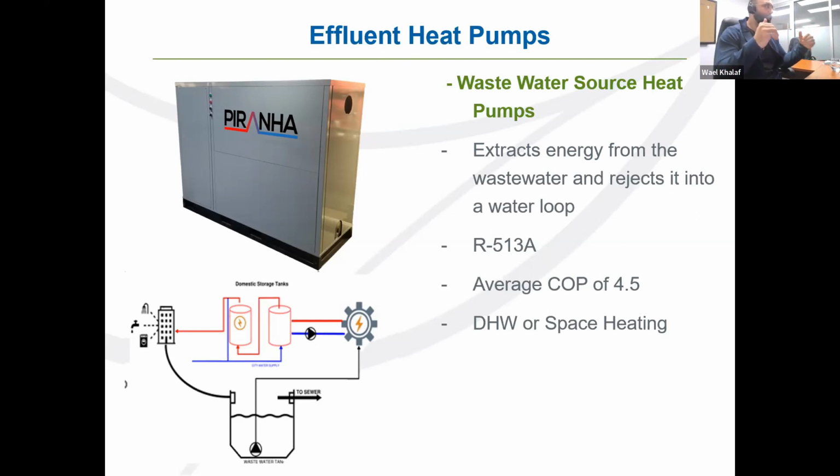And what this allows us to do is have a battery of wastewater energy sitting there, slowly moving through a pipe where we can take that effluent out of it, pump it into this heat pump, extract the energy, and then as soon as we're done with that wastewater, we just send it back to the municipal side. So the limitation in terms of permitting is essentially how you can install the wastewater storage tank, because in some municipalities the law is that you cannot impede the flow of wastewater if you're able to avoid it.